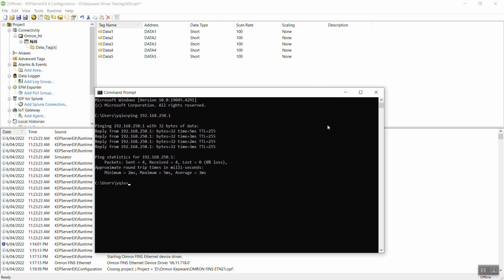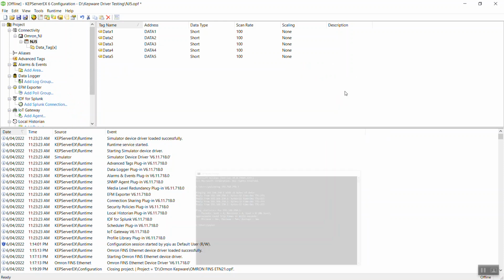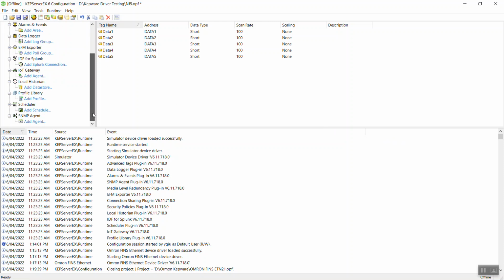So you're going to use Ethernet. The installation of the Kepware server is quite simple. You just download the KEPServerEX 6, the latest demo from their website, and then you install all of the drivers. Once we get it installed, this interface will come up.